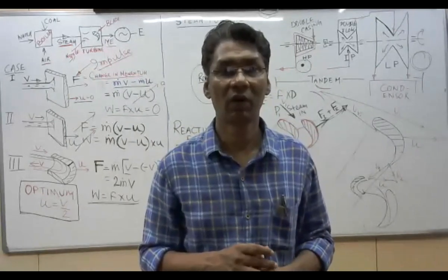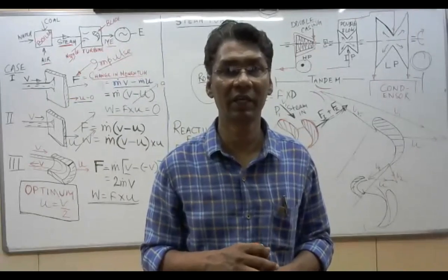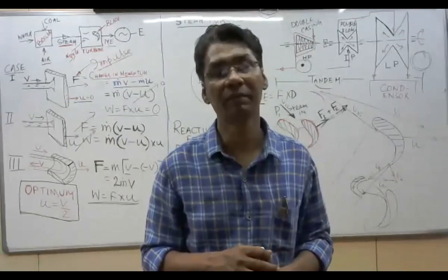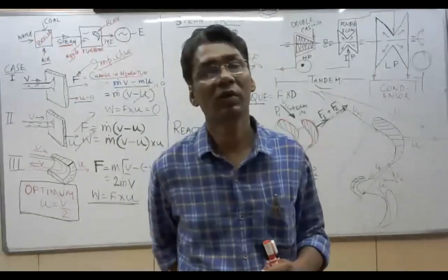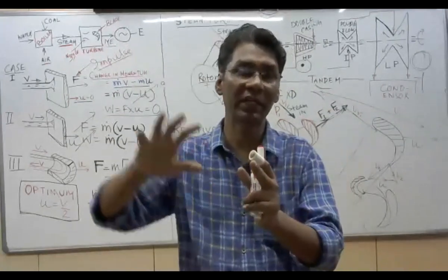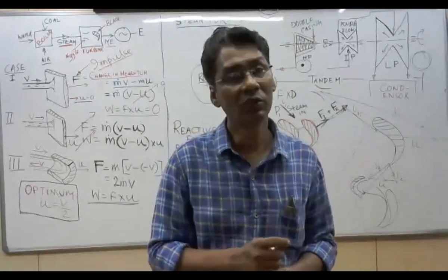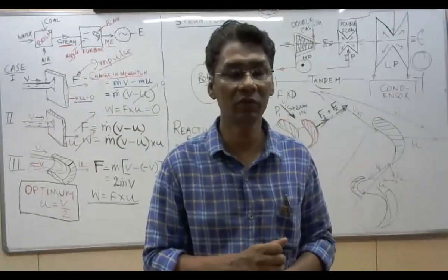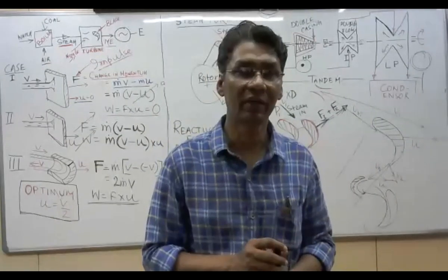Now first, why use a condenser? Why not use the expanded steam in the boiler directly? The condenser is to condense the steam and convert the steam into water so that it can be reused. A huge amount of DM water is used, so it cannot be wasted.